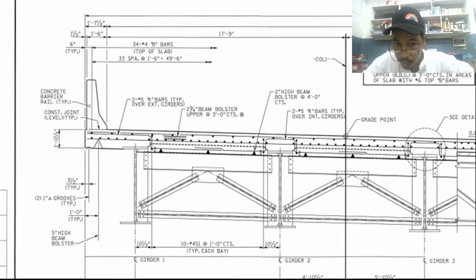That is what we mean by this. There are two of them. So meaning, if there are two of them, it only means that the bars above and below this series of black dots are the same. They are both number 5 reinforcing bars. Okay, that is what we mean by this.